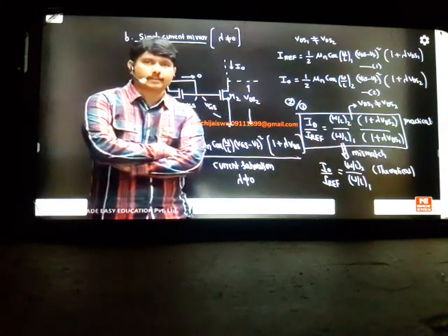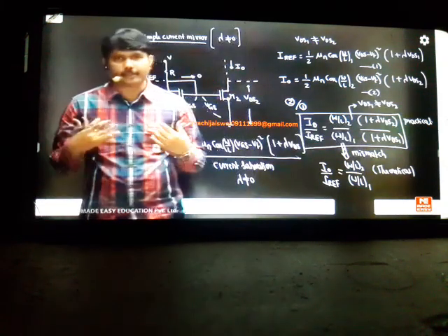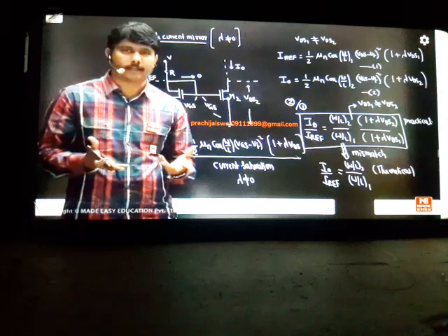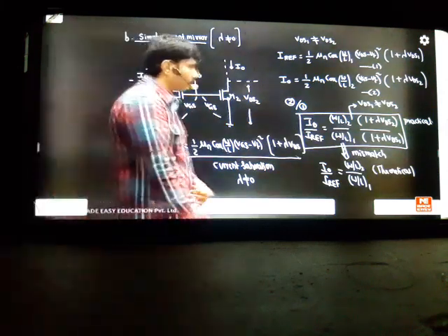Yes, Rahman, in the previous case also VDS1 and VDS2 are not the same. But it did not matter, because lambda is 0 there. We got lambda 0. So even though VDS1 and VDS2 were different, we still got the W/L1 by W/L2 ratio, and we enjoyed it. But here we are not enjoying it. Okay, Rahman? So let us complete the final task.